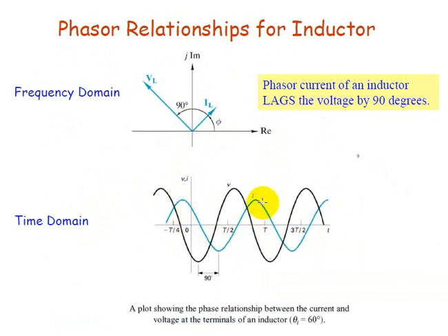This is the applied current I, and here the response, the voltage, and you can see there is a 90 degree shift in the current and voltage relationship. We can easily see this shift in the frequency domain, or the other way, if we measure the frequency and the shifting part, we will also get the 90 degree shift. Here you can see these two peaks are actually 90 degrees shifted. This is the time domain response of an inductor.